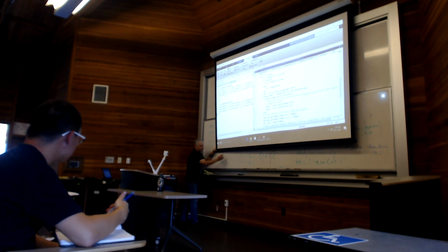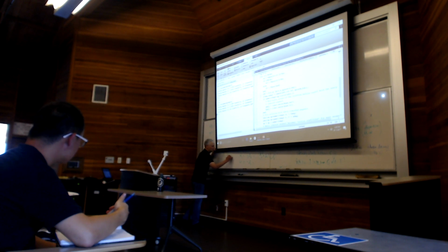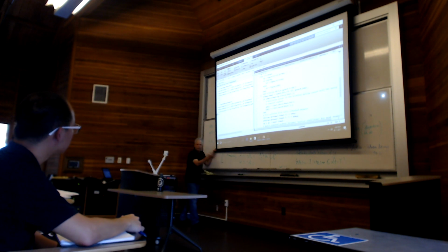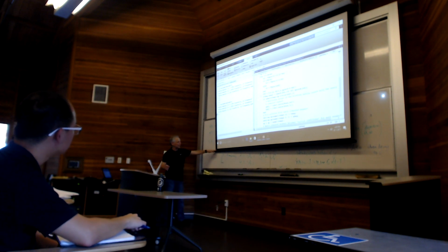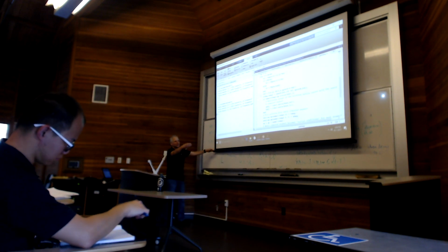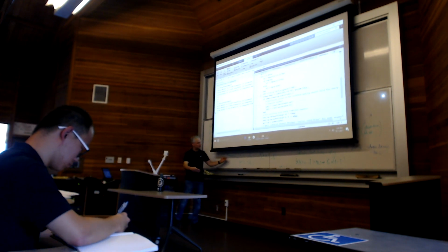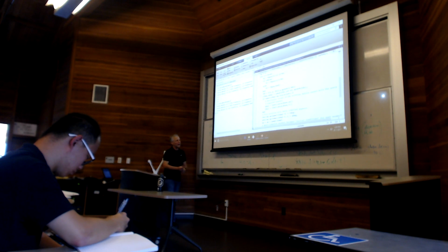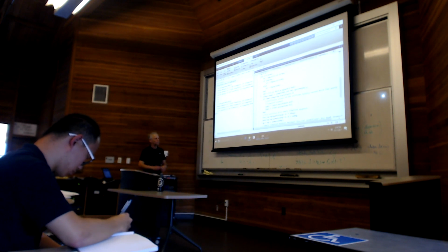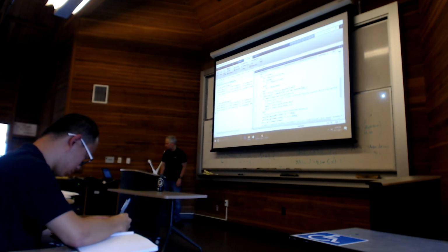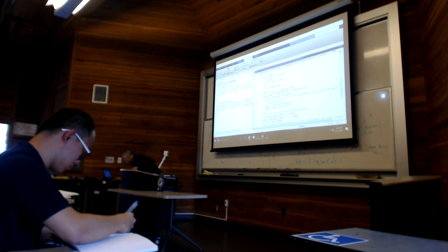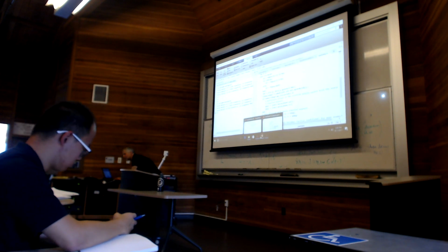And if you look through the help, you'll find what library that's in. Then you can drag out a delay block and delay one signal from the other. You'll see that the output is just a delayed version of the input. And if you put in a long enough delay, you'll screw up the simulations that you've been playing with so far. Okay. Any other questions on that?